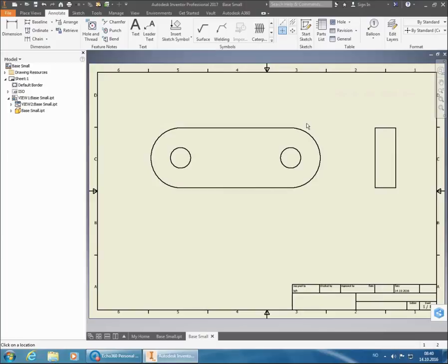And then we have to remember to both put a center mark on the curved edge of the plate and also on the hole. Because if I only put on the curved edge of the plate, then I only get 3 lines. I don't get a line extending out on this side of the hole. So I have to also click on the hole to get that third line and that fourth line extending there.